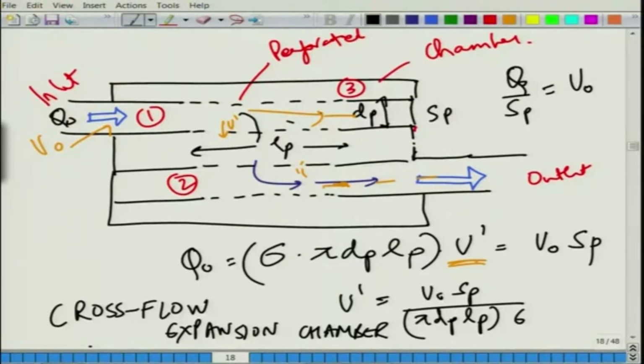So, this will be 0 here, from the maximum value it will go to 0, and in the process your bias flow will be non-zero here, entering this perforate, and you will have some non-zero convective value in the central duct as well, which we have conveniently ignored. Then we pick up from 0 value here to a maximum value here in the outlet duct. So, the idea is that the flow is gradually varying.